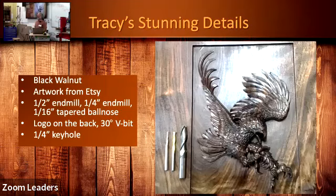Yeah, well, I do a really rough sanding with a real fine 500 grit. There's usually some fuzzies, and sometimes mops or something will take them off. I did a little bit more sanding on my work. Also, if you were to do a bigger step over, let's say like 10%, 12%, you're going to see lines through, because it's not going to clean that up. That's why you have to do that. Tracy speaking to the advantage of getting this stunning detail by using small step over gaps.